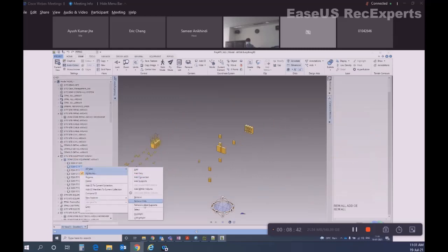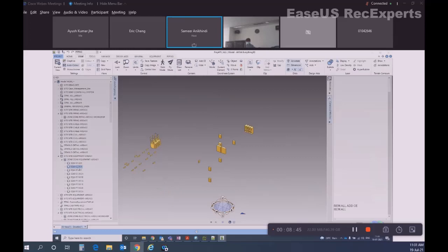Right click. You can say reduce, select. I think it didn't add. Sorry. Okay, it is here, but it is not visible. So the view, it has been added, but sometimes it happens that it is not really visible. It appears to be distorted or cut somewhere. So you have to just right click and zoom extends. So it will be visible. So that was out of the camera. It was not visible properly. So you have to right click, zoom extends. Okay.